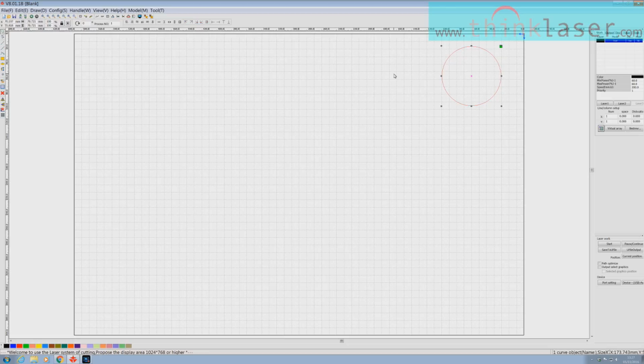So I think for convenience purposes, we will leave the green dot up at the top right hand corner of all the geometry that we're going to use, because that way we will know that basically we're trying to always generally set things over here at the top right hand corner of the work table, and then everything will grow out to the left and downwards. So that's what the green dot is. The green dot is the 0, 0 point for the program that's going to be written.